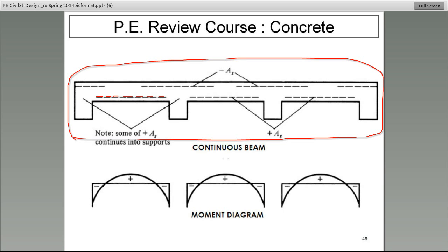All right? So these problems that they give you, they say, well, where should the steel be, or which one is correct? This is what you need to do. You need to identify where the beam is in tension. And sometimes the tension side of the beam can be on top, not bottom. All right? So, for example, in a problem like this, remember what I told you?